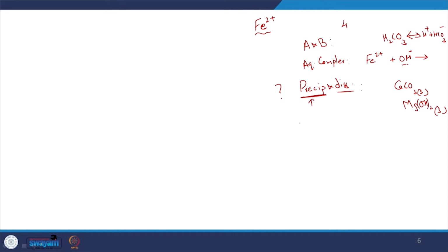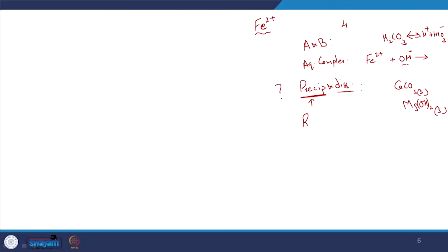Another aspect we briefly touched upon in the wastewater topic was redox, right? Redox as in transfer of electrons. You are going to have reduction and oxidation going hand in hand. In the context of wastewater, the reduced compound was our waste, CxHyOz, and the electron acceptor was oxygen, and then the final products, if everything goes according to plan, would have been carbon dioxide and water.